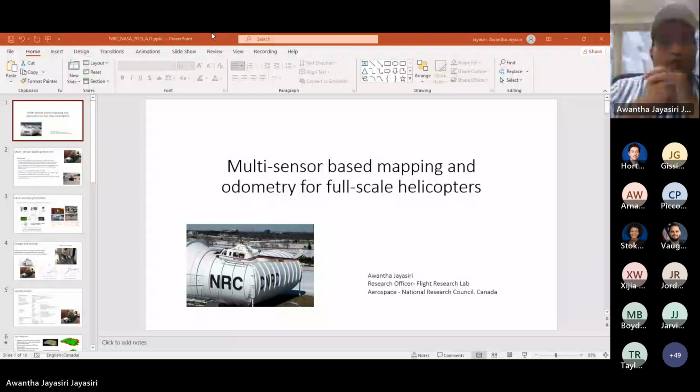The multi-sensor perception is achieved by using an architecture called visual inertial LiDAR odometry and mapping. You use sensor information like LiDAR, camera, and IMU and fuse them together to provide position, orientation, and mapping information.